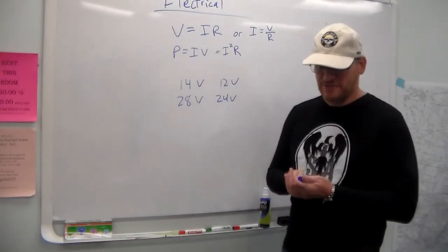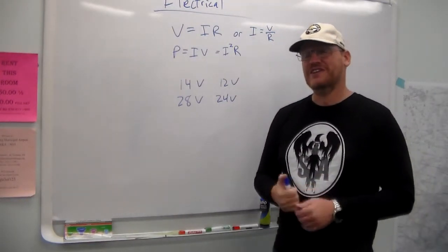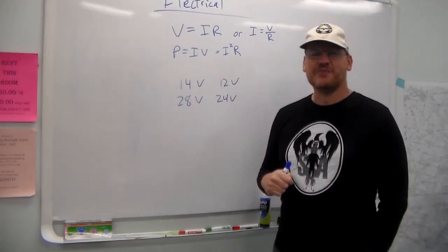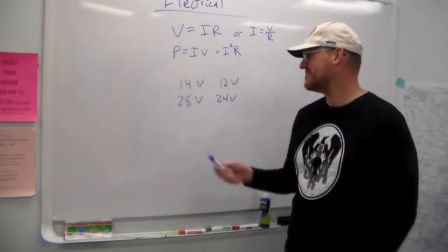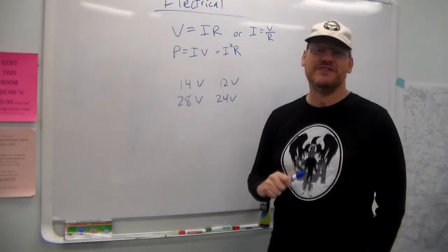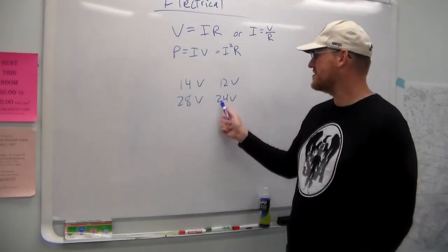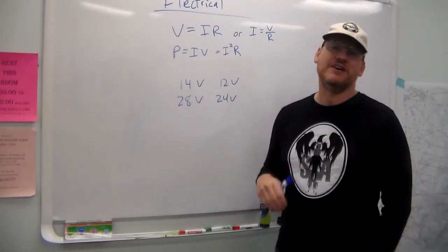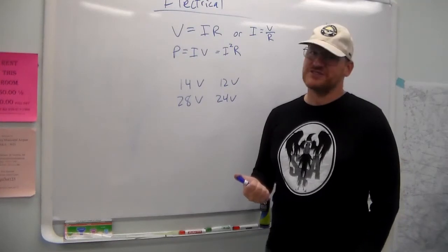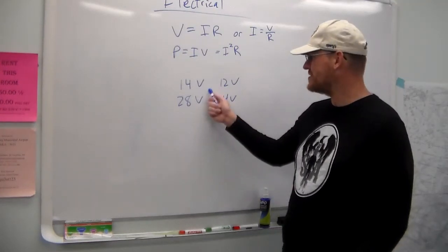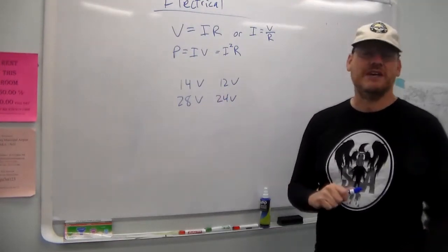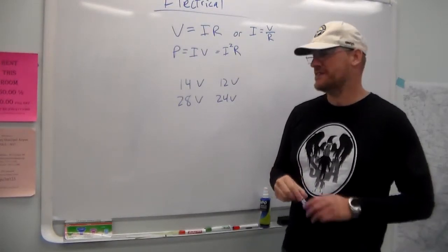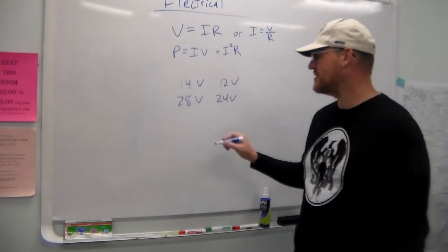Well, you have to have more pressure, if you will, in your pump to fill the tire than the pressure you want. Same thing is true with your battery. If you don't have more voltage than what the battery has that's being pumped out, the battery's not going to charge.